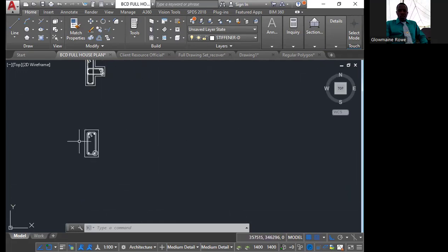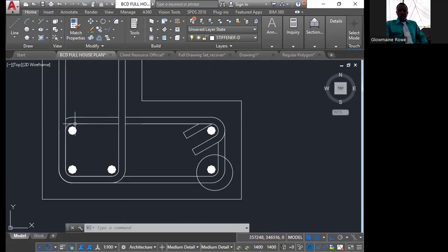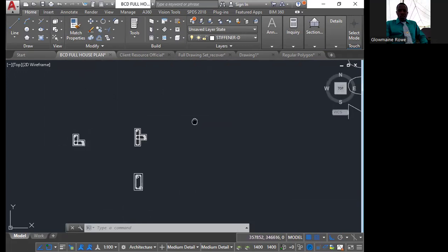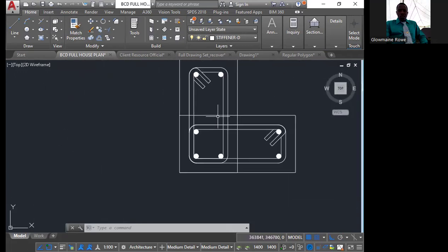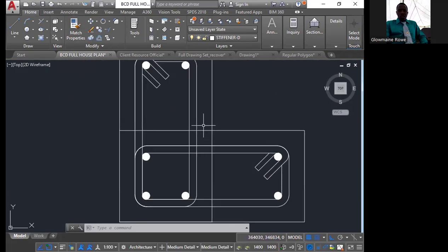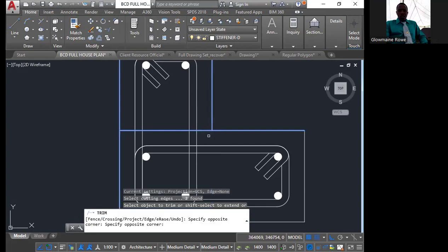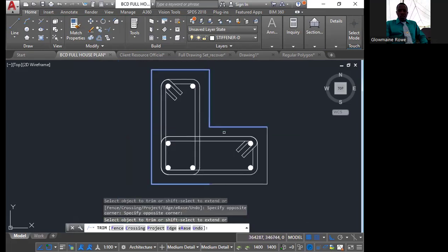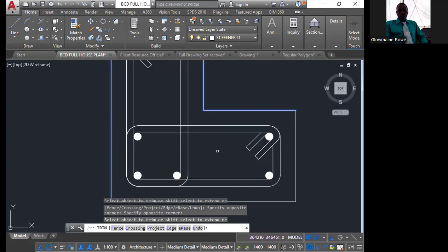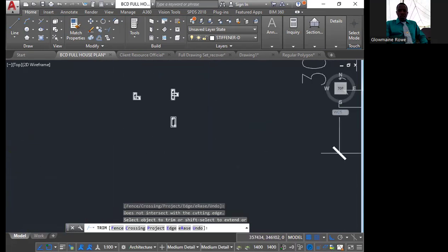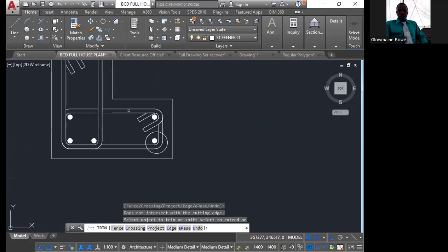to make it resemble this piece here. So recognize that the curved piece goes behind. So let's trim up so it looks like that. TR, enter twice. All right, better yet for here, we can just highlight and trim. Trim. Trim. So let's see which one goes behind. All right, so the new one goes behind.